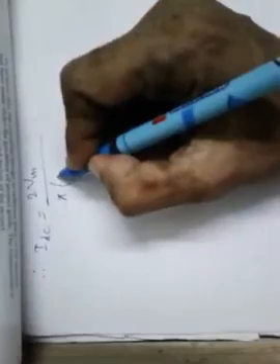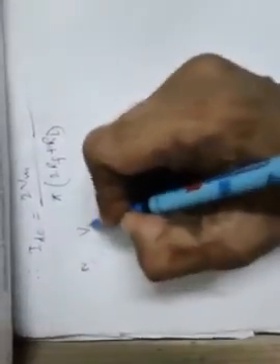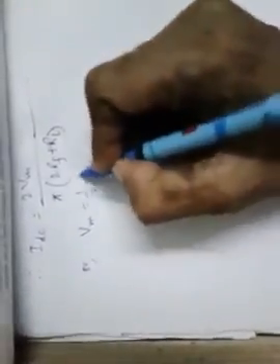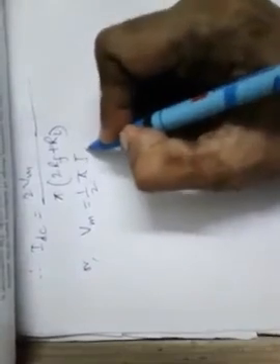Now if we combine the last two equations, we can write IDC equal to 2Vm by pi into (2Rf plus RL). So from here we can calculate Vm, which is half pi IDC whole into (2Rf plus RL). Now put all the values. IDC is already given in the problem, 124.49.